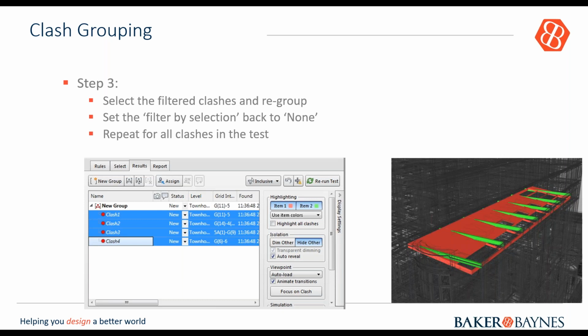And now the result for a grouped clash report is what you're seeing on the screen. In this case here, if I just show you, this floor slab would be the selected component, and everything that is clashing with it will be included in that group. Right? I hope that made sense for you. Okay. And Navisworks will see that as one clash group, and you're able to then report on that instead of reporting on 1, 2, 3, 4, 5, 6, 7 clashes. You just have one clash.